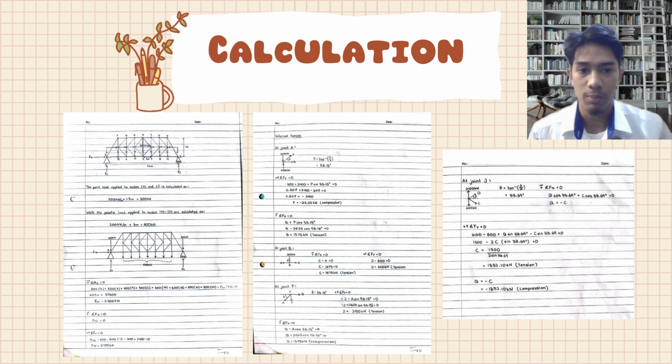The truss structure span is 24 meter and is subjected to uniformly distributed loads, converted into point load for ease of calculation. These loads are applied to nodes A through I. For nodes A and I, the point load is 200 kN per meter multiplied by 1.5 meter equals to 300 kN. For nodes B through H, the point load is 200 kN per meter multiplied by 3 meter equals to 600 kN. These point loads are applied vertical to each node.